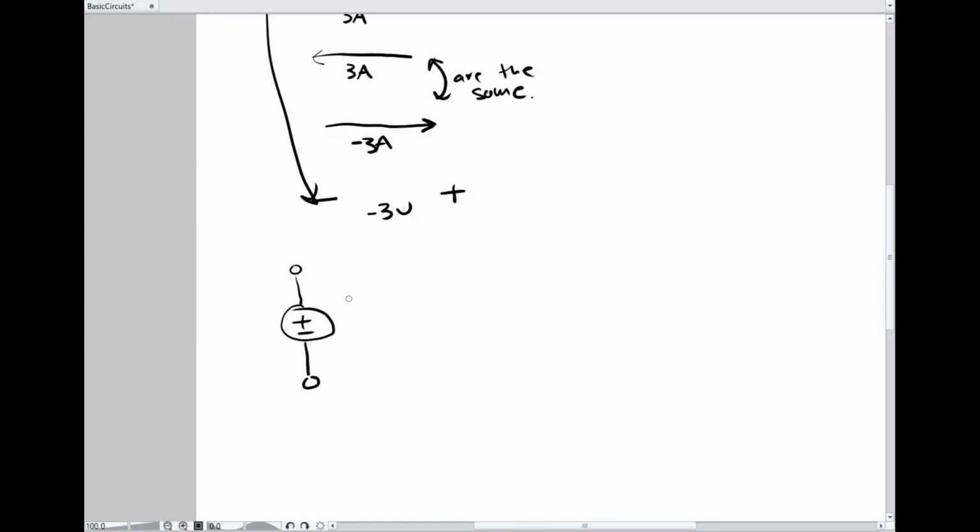An independent voltage source is defined in this way, that it specifies exactly and strictly what its voltage is. So for current we represent it with the letter I, voltage we represent it with the letter V. And it tells me absolutely nothing at all, this tricks students up, nothing about how much current is going through it. Current can go through it in either direction and to any degree, right?